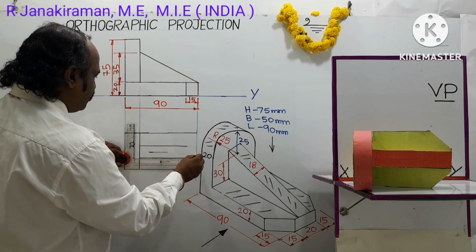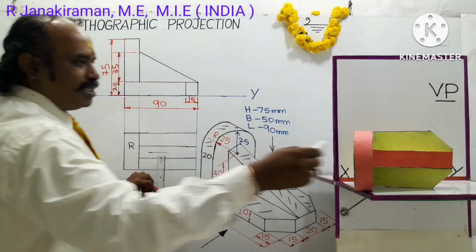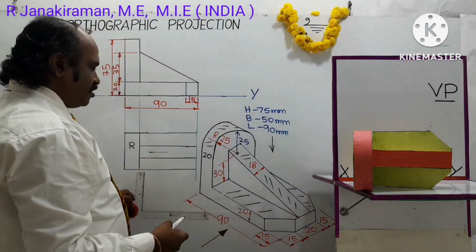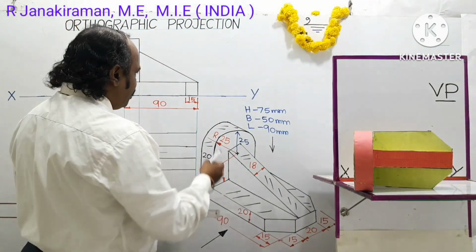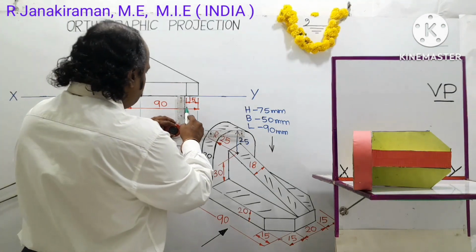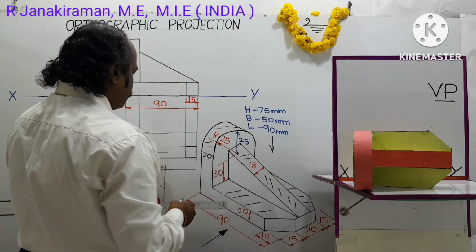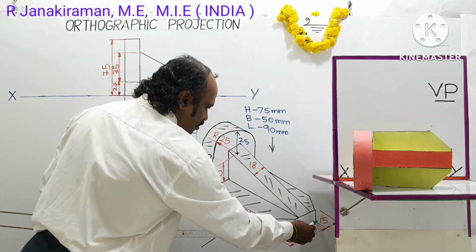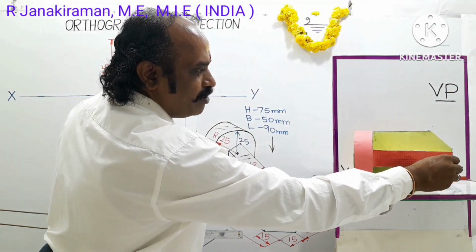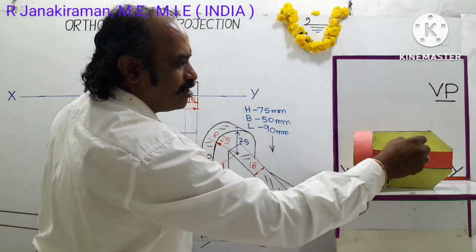Up to the end of the rectangle, these two parallel lines shall be drawn. And here one cross cutting is there, one on the left side and one on the right side. The distance is taken from the diagram. Okay, you trace it from the previous front view. Okay, and here 20 mm is there. This 20 mm is that portion shown yellow in color. In between this 20 mm, this 18 mm thickness of the triangular part lies.